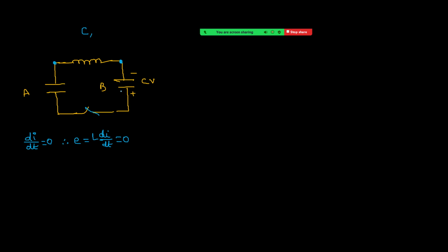That means A is now correct. Current in circuit maximum, charge on each capacitor is the same. And you see the CV value given is how much? Given 100 millicoulomb. That means this charge divides now equally. So here 50 and here 50. Okay, right.